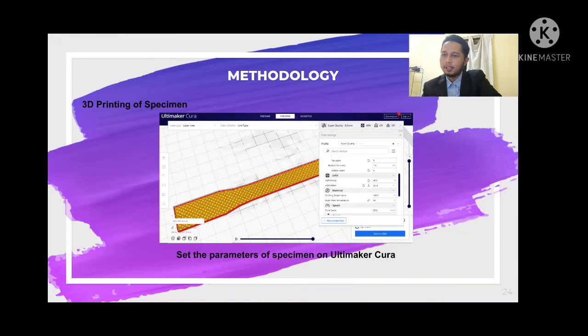Next is the 3D printing of the specimen. Transfer the STL file of the 3D model of infill density at 100% into this software. This is because the Ultimaker Cura is a slicer software that can set the parameters of the 3D specimen before printing it. Thus, no need to import all the different models. Only a solid model will be sufficient. The file is then turned into G-code, saved in a micro SD card, and slotted into the 3D printer.